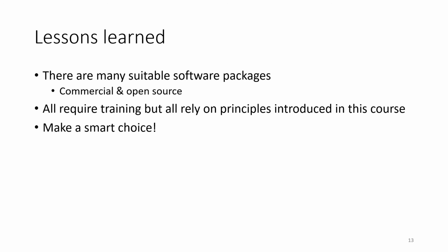Don't get fooled. Of course, every software needs training, right? But if you, with this course, understand the basic principles of numerical modeling in a groundwater context, this applies to all of those software, right? So the Péclet number or the Courant-Friedrichs-Lewy stability criteria, or in general the problem of numerical accuracy, the terms of spatial discretization or temporal discretization, the mathematical background, this all stays the same. So what you have to learn is only how to use the software, as the background you already know.